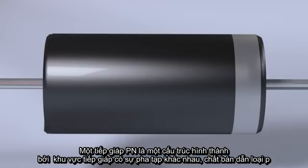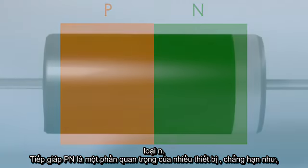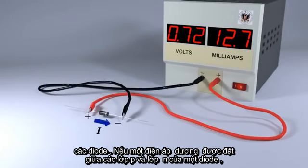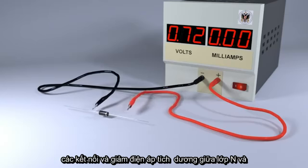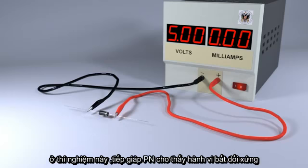A p-n junction is a structure formed by neighbouring regions with different dopings, p-type and n-type semiconductors. The p-n junction is a crucial part of many devices, such as, for example, the diode. If a positive voltage drop is applied between the p-terminal and the n-terminal of a diode, a large current can be observed experimentally. If we change the connectors and a positive voltage drop is applied between the n-terminal and the p-terminal, an extremely small current, negligible for most practical applications, is observed experimentally.